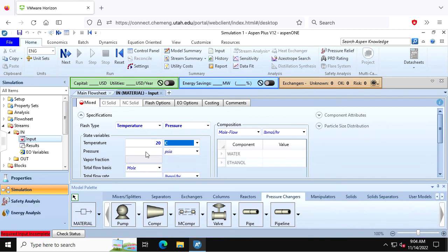So if you go down 34 feet, that's 1 atmosphere. So how many times does 34 feet go into 120 feet? Roughly. I want one significant digit. 4, right? How many psi is that? 60, okay? So, and maybe add on a little bit. So maybe it's like 55 or something like that because you divided by 34 instead of 30. These types of things are useful to be able to do in your head. You got to remember all these wonky translations, but 34 feet per atmosphere.